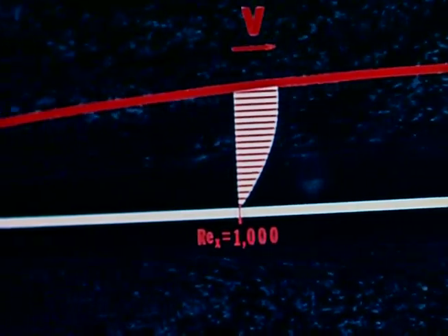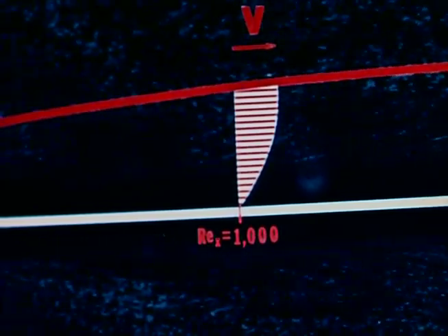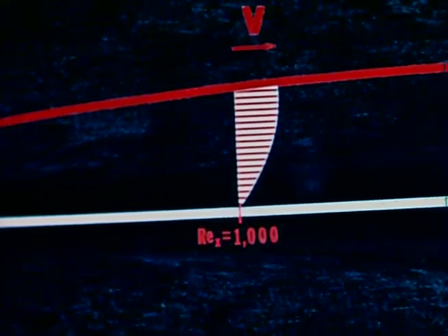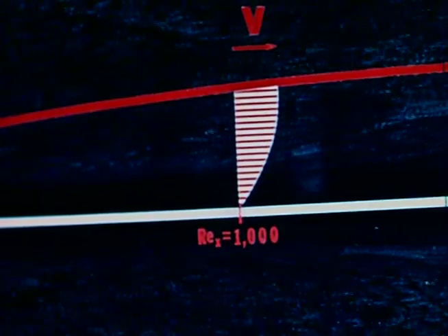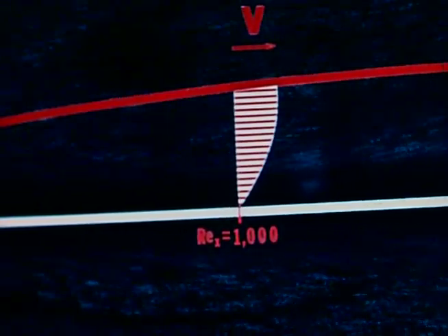The flows we have been looking at are laminar flows, but laminar flows and their associated theoretical formulas cannot be extended to arbitrarily large Reynolds numbers. Rather, the boundary layer becomes thinner at a given x distance as the velocity is increased or as the viscosity is decreased, and the shear stress or friction at the wall increases until the boundary layer bursts into turbulence.